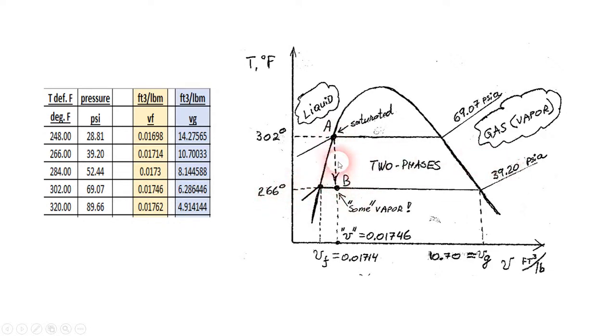And why does it suddenly drop? It suddenly drops because we just explained that steam is no longer coming. Cold water is cooling the entire DA liquid. And as it's cooled, it's moving from A to B along the constant volume line, because, as we mentioned, the control volume of the entire DA and piping is constant. So as it's coming down the line, not to the right or to the left, but straight down the line, by the time it gets to 266 degrees, it'll be some fraction X, a certain amount of vapor and a certain amount of liquid. Mostly liquid, but some vapor.